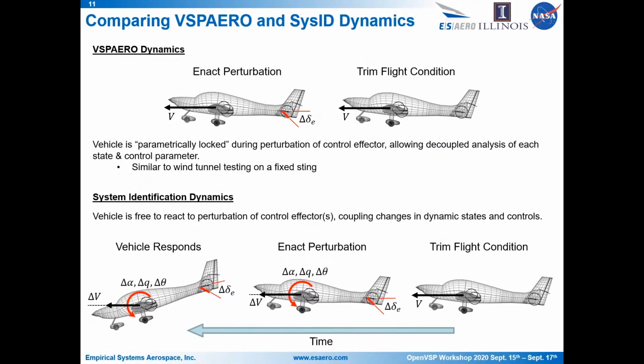And in addition to looking at the models themselves, we have to reconcile the concept of what is actually happening when we linearize or attempt to linearize forces and moments between the two approaches. And this probably is the largest takeaway from our work thus far, where in VSPAERO, you can set the vehicle to a specific trim flight condition and run analysis on that.